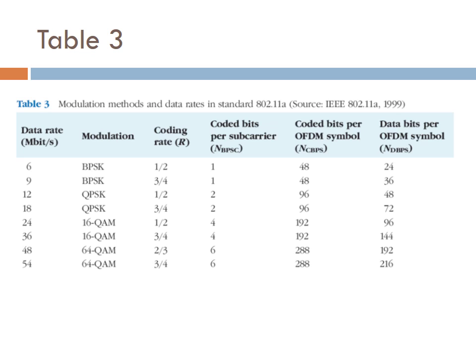Note that one consequence of coding is that the data rate at which a device operates is not the rate at which a file of data is transmitted. For instance, if you have a 54 megabit file to transmit over a wireless link that is operating at 54 megabits per second, it does not follow that your file will be transmitted in 1 second. The coding means that the amount of data to be transmitted is significantly more than 54 megabits and will take significantly longer than 1 second.